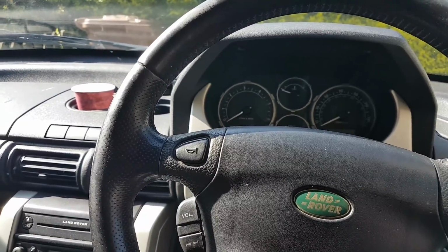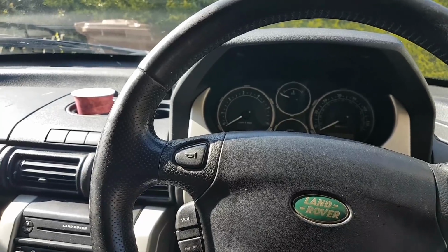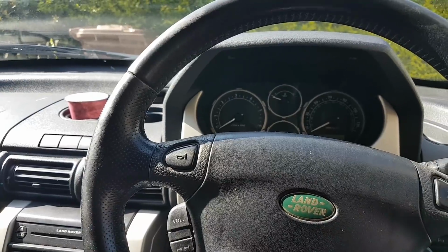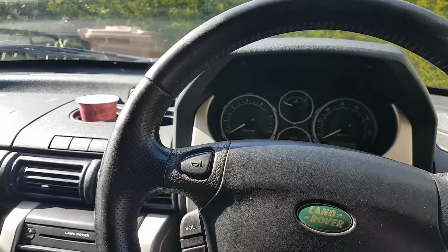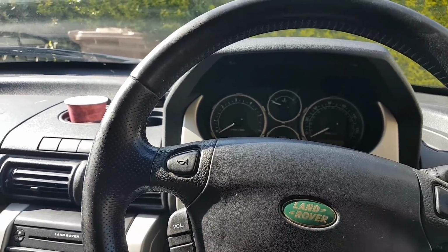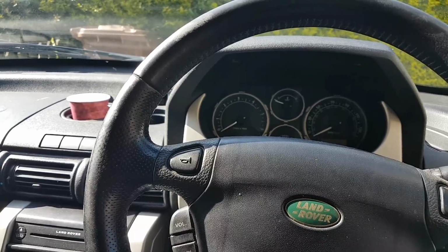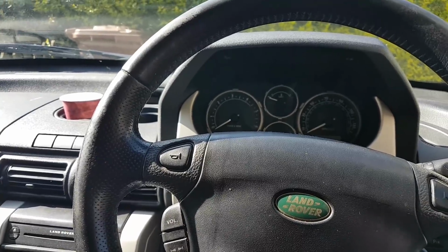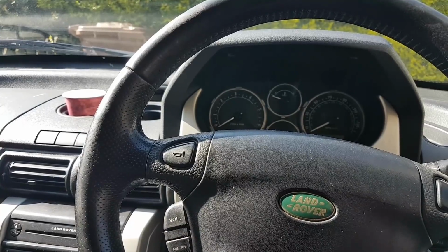I engaged reverse and drive, and it drove fine, but I only drove the car to maneuver it here on my driveway. I never actually went on a road test, which I'm going to do in a minute. So the complaint is that when you start to drive, it goes into limp mode. We're going to go for a road test and see exactly what happens. But I've scanned the car and deleted the codes because there were loads of codes in there. And obviously if it triggers any codes, I want to see exactly which codes they are.